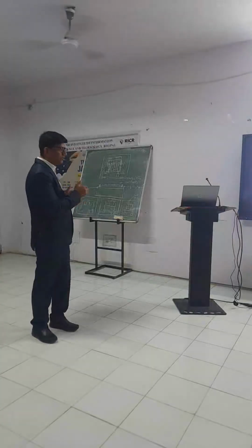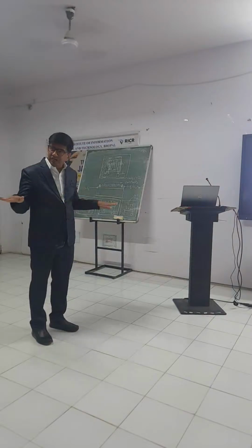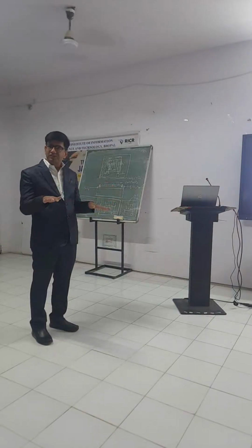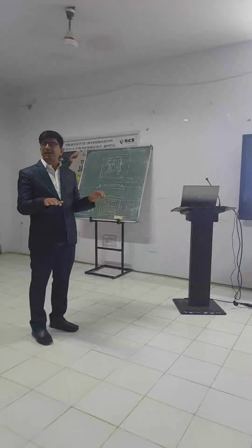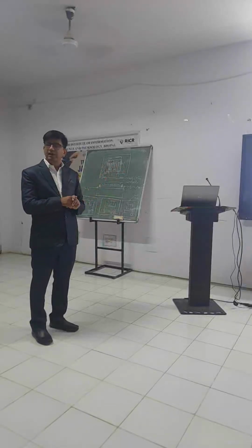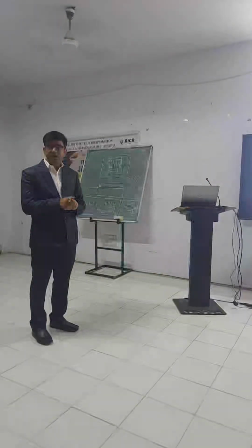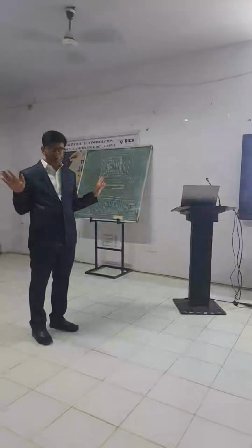Then after the nickel and chrome, what are we depositing? We are depositing an oxide layer and again patterning this oxide layer, and we will see whether this oxide etchant is compatible with your nickel chrome or not. If it is compatible, again we will go for bright field lithography. It means we do not require any lift-off process.